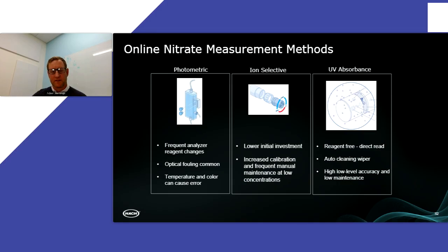So just finishing up on total nitrogen, I talked a little bit about it before, but we've focused quite a bit on ammonia. So I want to just take a minute and talk about nitrate. When we have limits, total nitrogen, total inorganic nitrogen, those include nitrite and nitrate. And so at a facility, if you want to measure and get a good sense for what total nitrogen is in your facility or in your aeration basins, if you were to measure nitrate and nitrite, or nitrate only, and ammonia, you're going to get a really good sense for the majority of how your process is treating for total nitrogen and total inorganic nitrogen.